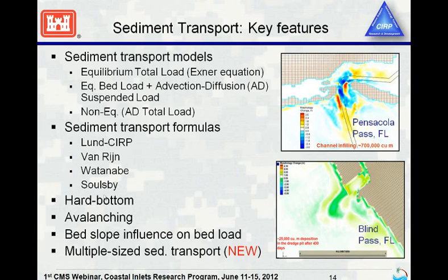And so we make those options available to you. You can also turn on a hard bottom if you're working in some parts of the country where the sand is really limited once you get down to a certain level because of rock or other types of hard bottom. So you can specify that. We have avalanching. We can change the influence of the bed slope on bed load equations. And then most recently we're adding in multiple size sediment transport. So you can do different types and sizes of your grains. And Alex will be discussing that at next week's webinar.